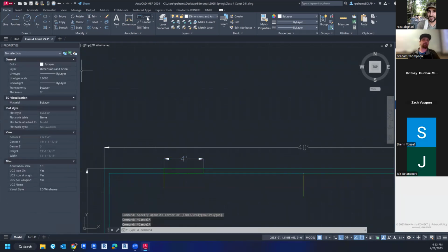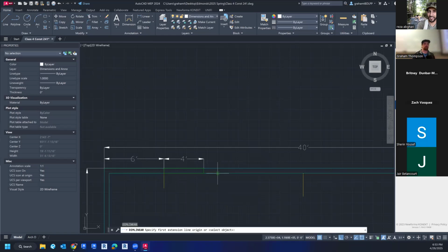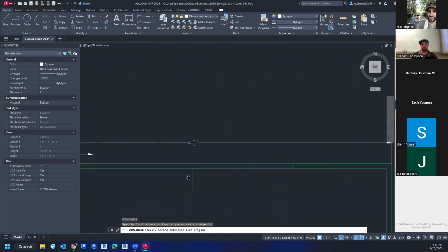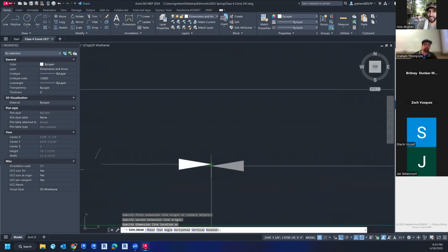And if I use my dimension tool, right? Linear, 1, 2, set it. Okay, enter. Now that command is done, right? If I hit enter on my keyboard, it will automatically do the last command that you just did. So if we need to dimension this, like, and last but not least, you can come back in here and actually snap those arrowheads together if you want to.